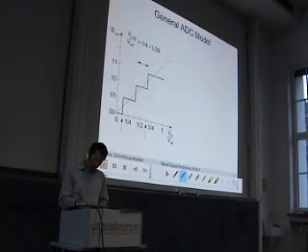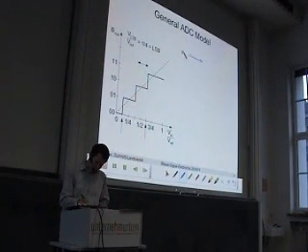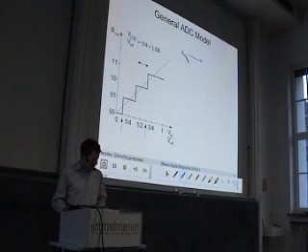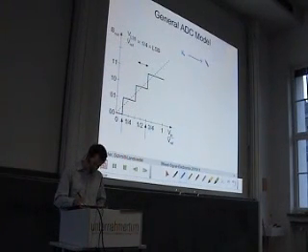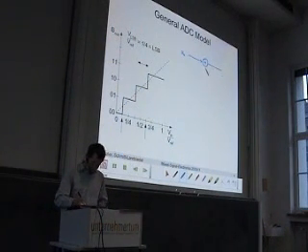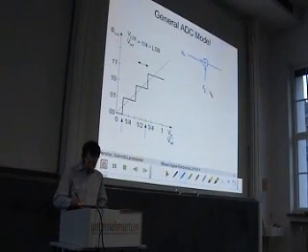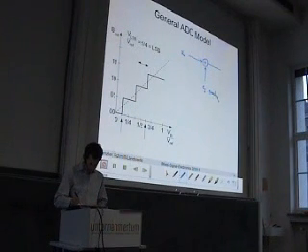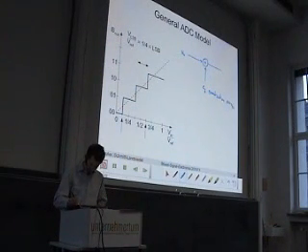So, you know, the goal of an A to D converter is to take an input voltage, V in, and to convert it into a binary word. And a very basic model is to say, we take this input voltage and we add a quantization error E to the input voltage. This is the quantization error. And this gives us the digital output word B out.